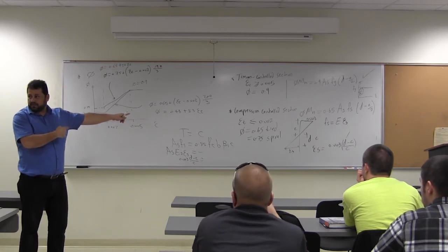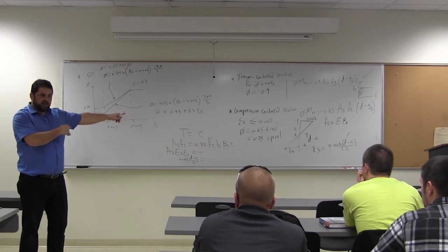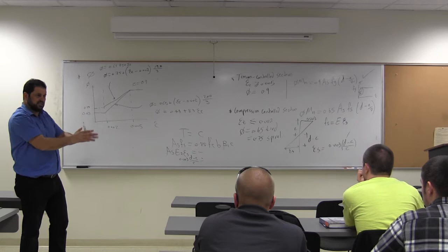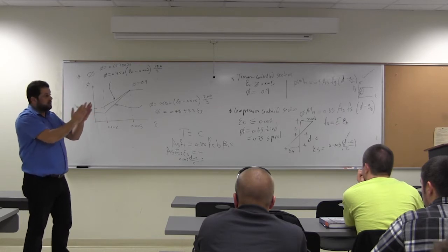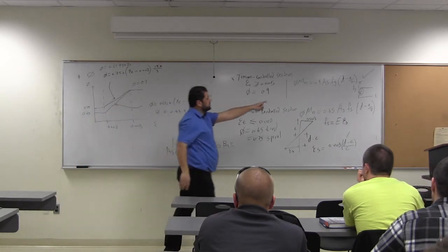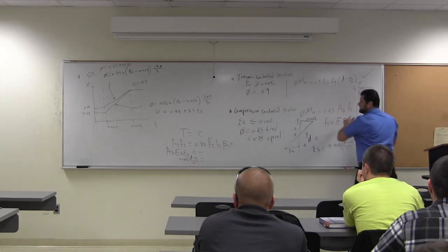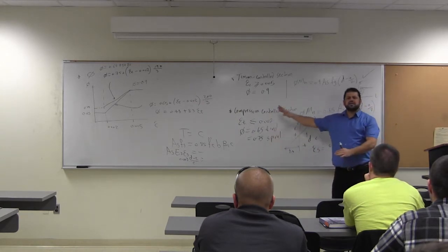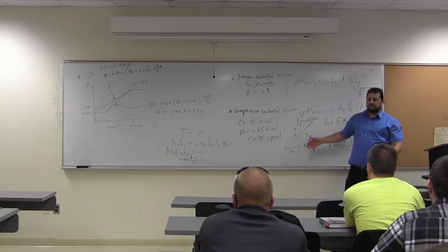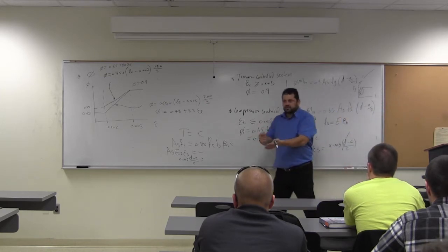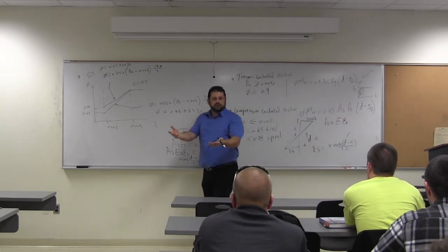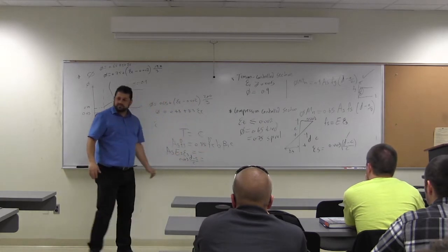If the strain is more than 0.002, it means the steel yielded, means Fs equal Fy. Below that, you are in the elastic region. That's the analysis of a compression control section. So easy, not a big deal. The only thing is just the quadratic equation, you just put it in the calculator and you're done with the new calculators. Or just solve it.